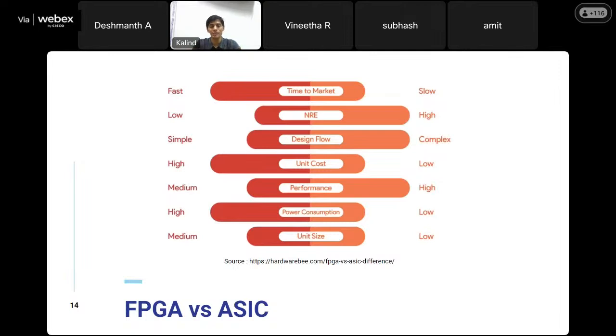Whatever circuit you have to implement, as we talked about in the first slide, the electronic design process, you will create the layout first. You will make sure that your entire schematic is ready. Then you will make sure you make the right choices of components. Then you will make sure they are placed correctly. Then you will make the interconnections and so on. All that you can do on an FPGA first. So you will use an FPGA to make sure that this entire chip, what it is supposed to do, you will implement that entire logic circuit in your FPGA.